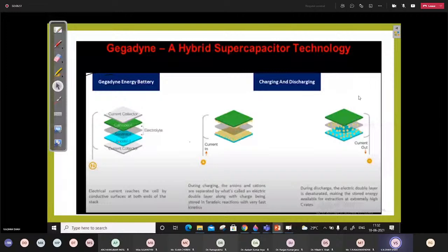So this is a parallel connection. The battery and supercapacitors are connected in parallel. Now you can visualize that if both are working at the same voltage level, then the capacitor, as it has low resistance, starts supplying power to the load. But as soon as the supercapacitor voltage becomes the terminal voltage of the battery, the supercapacitor cannot deliver power to the system.